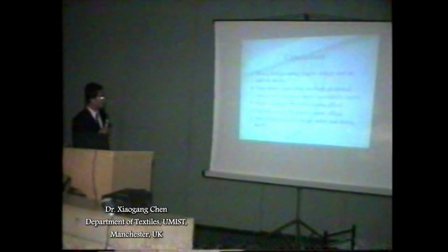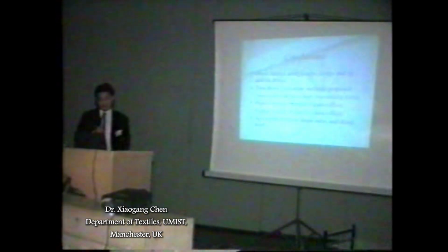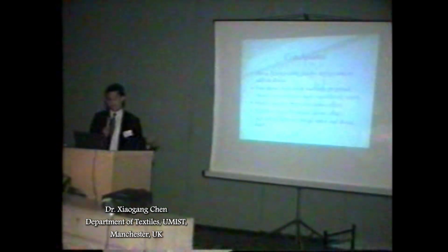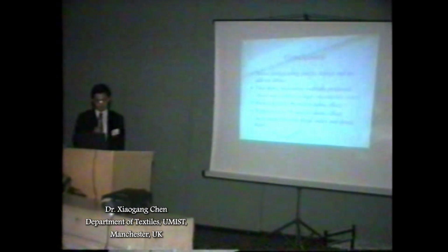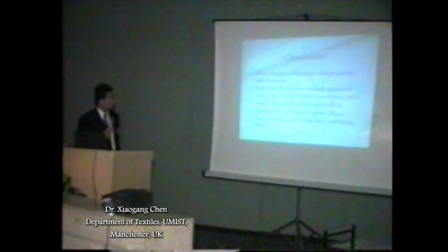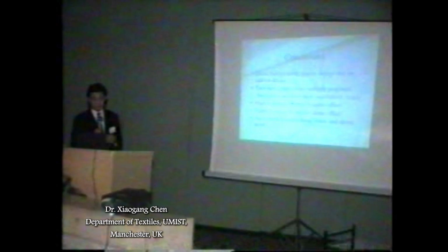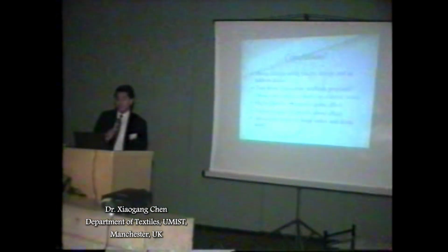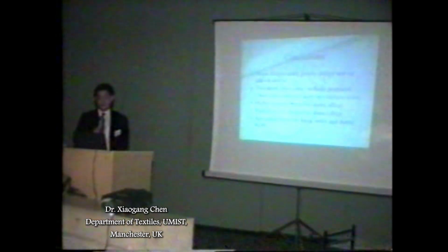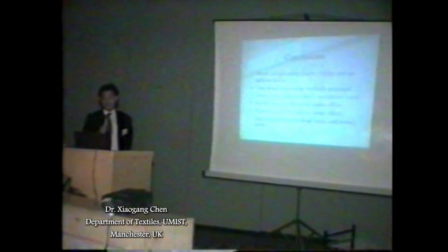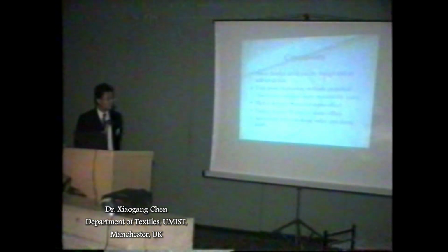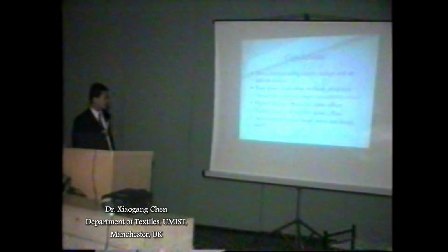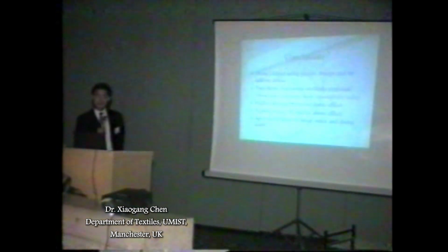Right, so to come to the conclusion. We have produced dome fabric using two different methods: patching design and an add-on device. Then two dome evaluation methods were used, the dome index and dome depth. What we saw is that the higher the density, the smaller the dome effect. The tighter the weave, the smaller the dome effect. Also, we have seen a very good agreement between the dome index and the dome depth.